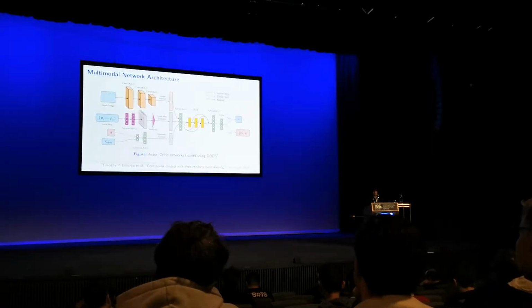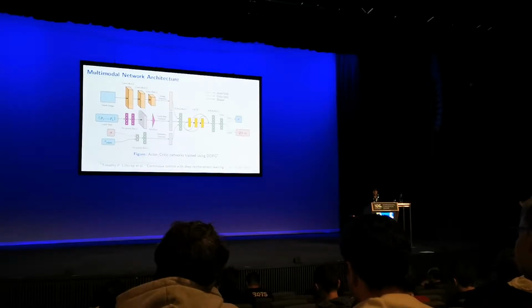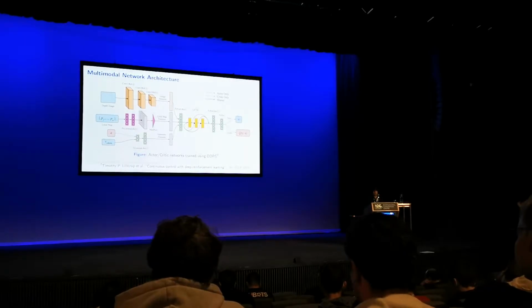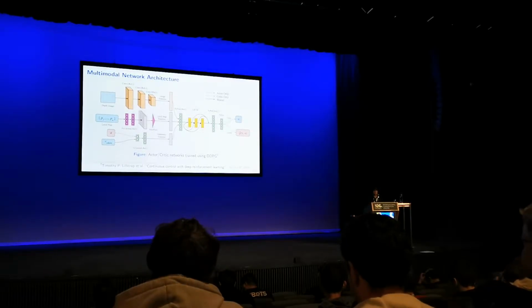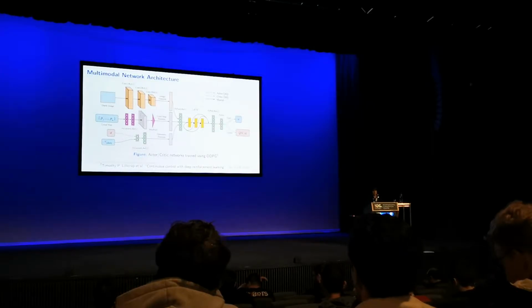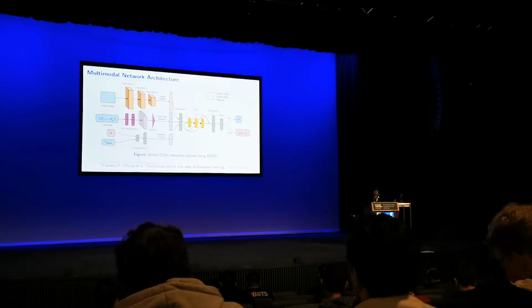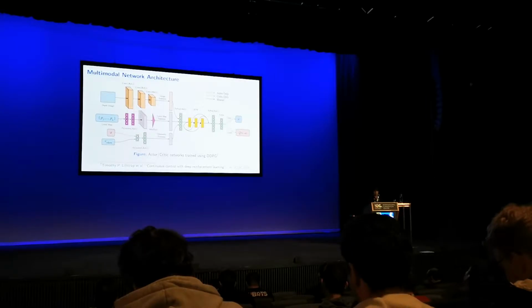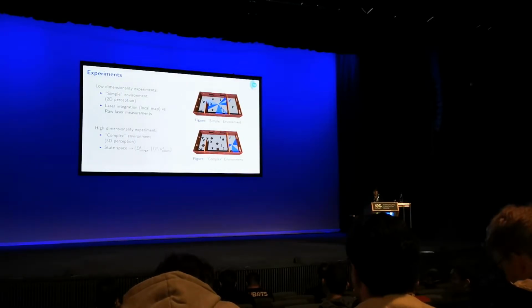So what we do with the PointNet module is to actually process every 2D point in the local map separately with the same fully connected layer, and we stack all the features resulting from this processing to then use a max pool, and that way we can always have a fixed dimensional representation, and we can then feed the concatenated features into an LSTM to be able to integrate information through time to estimate the actual state of the robot with several observations.